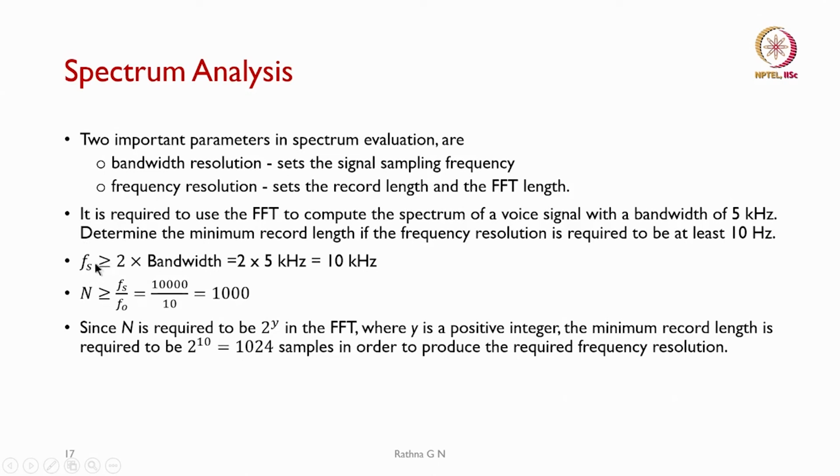Our sampling frequency has to be greater than or equal to twice our bandwidth, which restricts our sampling frequency to 10 kilohertz. Then we will see what our record length n is, which we have to calculate.